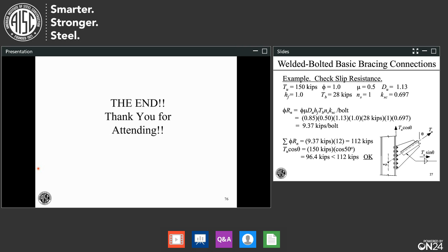That's a really good question. I've never seen that done before. I would say typically I probably wouldn't, but I could imagine a case where there's a whole bunch of bolts up and down this for whatever weird reason. And then with the Whitmore section, you could use some engineering judgment and decide to discount some of those bolts. I've never seen that done before, so that's actually a pretty neat question. But I guess I don't know. I guess tentatively I'll say probably not, but hey, who knows, maybe.